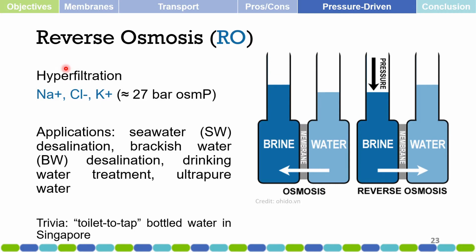In terms of application, RO or reverse osmosis has taken over the world, generally for the desalination processes. Around 80% of the desalination plants in the world are operating with a reverse osmosis process. I may consider this because most of these plants are small scale plants. So most of the application with membrane process is for small scale plants. And currently, this 80% of desalination plants can provide 50% of the total volume of desalinated water worldwide. So this is where membrane processes are getting bigger industrial applications in terms of the desalination process.